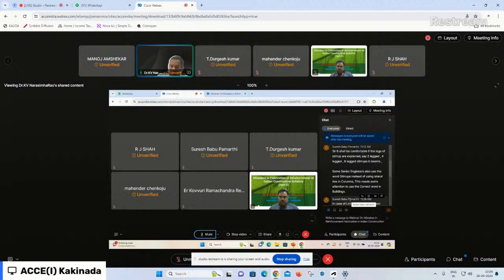For this, the edge conditions of the plate matter, that is, in terms of the stem placed into the raft. Suppose you can support on the three sides, or on the four sides, or within the three sides you can assume that there is a release of the movements at the plate. If you are assuming in the design stage that there is a release of the plate edge conditions, that becomes a cantilever action of the plate. In that case, you have to anchor the side reinforcement up to Ld/3 only into the column face, and not more than that. Once you are anchoring more than Ld/3, that leads to a fixed condition.